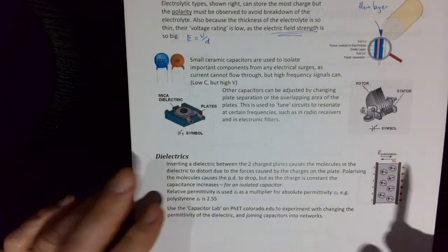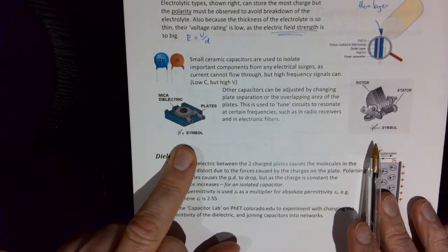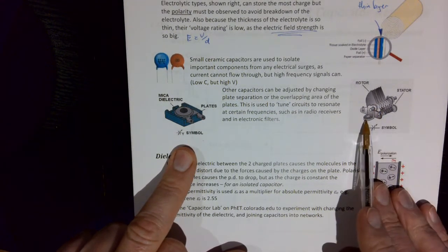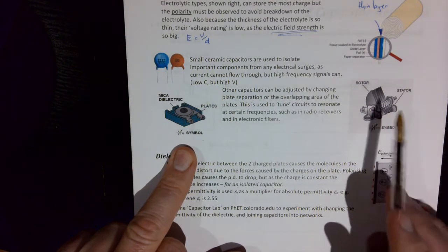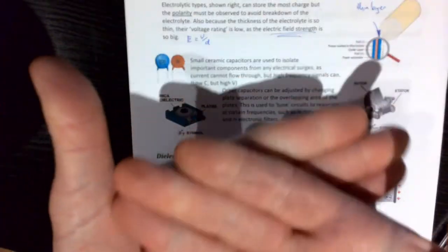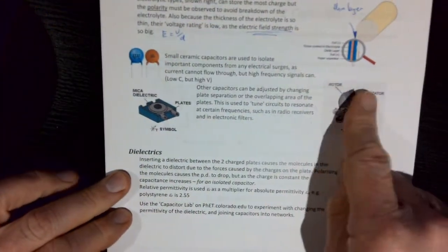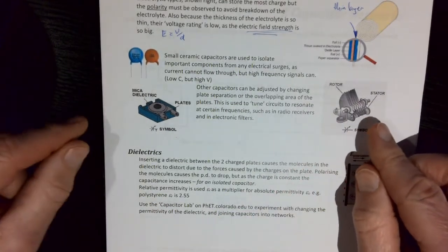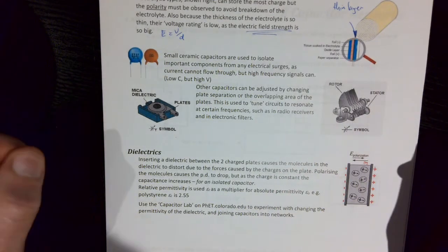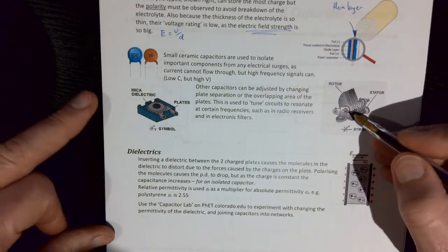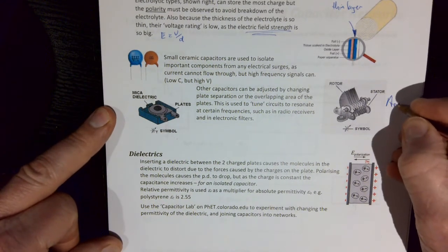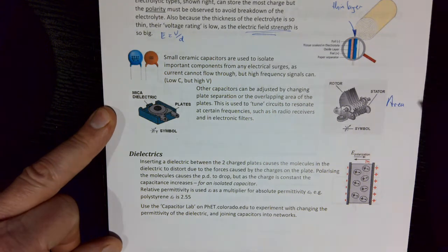Couple of adjustables, again using common sense, we can change the overlap of the area. So you can spin these round and our plates will cross over more or less, and it's the area of the crossover that matters. Okay, so that would give a bigger capacitance than that because there's only my fingers at the moment crossing over. So you can adjust them, and the size of the overlap is where the electric field forms, and that's what stores the charge. So area on that one, very adjustable because it's quite easy to spin.